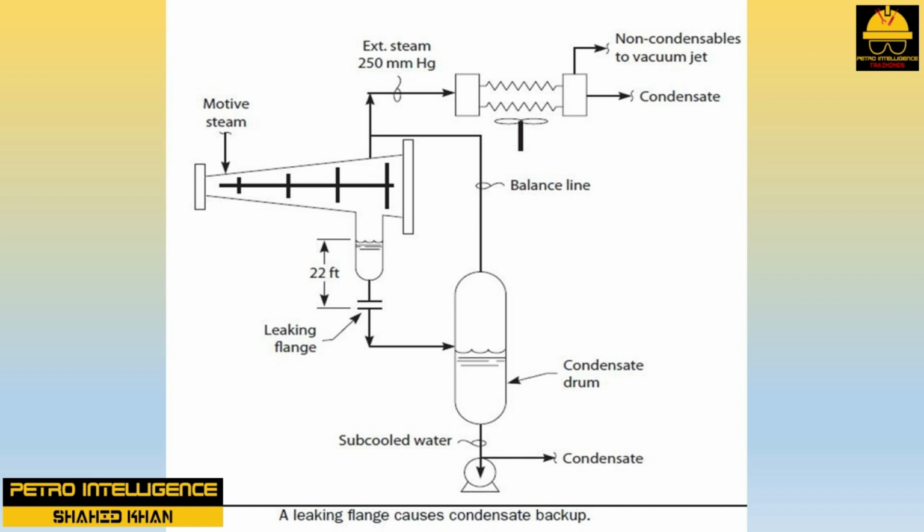This flange was found to be leaking. If the water head pressure at the flange became less than atmospheric pressure, then air was forced into the drain line. The bubbles of air expanded as they floated up the drain line into the turbine case. This prevented the water from draining freely through the drain line into the drum. Only by raising the turbine case pressure to pressure up the flange to match atmospheric pressure could this air leak be stopped. The flange leak was taped over, and the exhaust steam pressure dropped back to 100 millimeters of mercury.